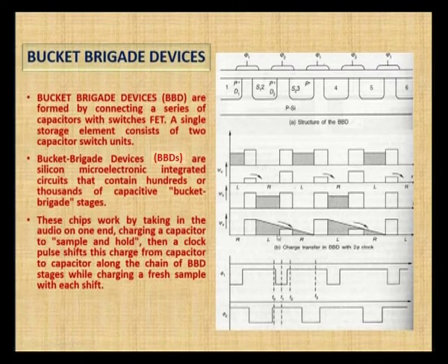At T1 you observe that phase 1 is lower and phase 2 is higher, where we find the charge higher, and it decreases toward the right one. Again the same thing happens from the left, where the charge will be more, and when it comes to the right it is decreasing. This is how the bucket brigade device works. From the animation you can analyze it even better.